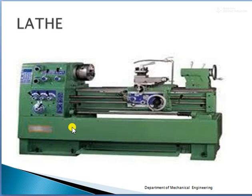Here is a simple example. We are going to have the tool post, the carriage, and the different parts. In the chuck we hold the job, and in the tool post we fix the single point cutting tool. Then the motion starts, and the tool removes the material from the workpiece. The chip moves ahead of the tool, and material removal takes place to get the required shape and size.